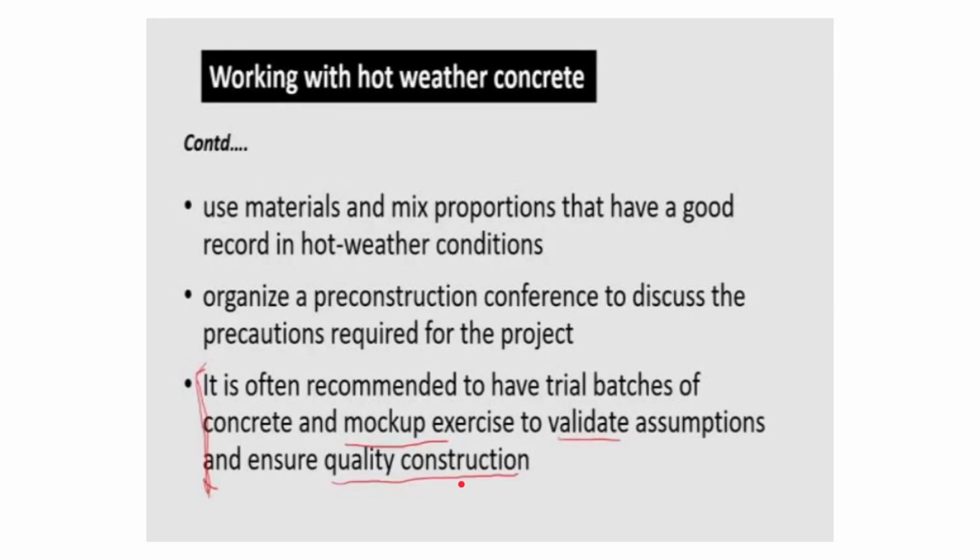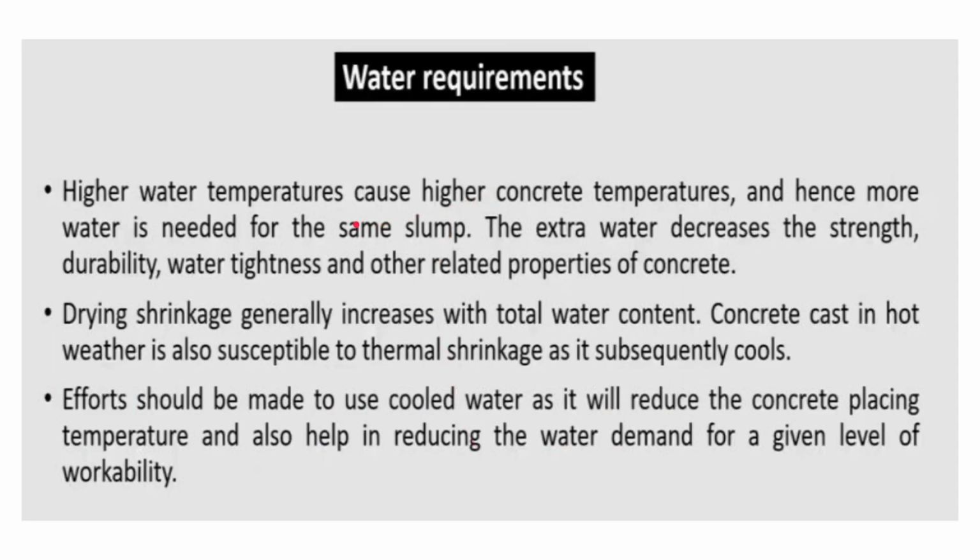Now let us come to the water requirements. As we studied, higher water temperatures cause higher concrete temperatures, and hence more water is needed for the same amount of slump. The extra water decreases the strength, durability, water tightness, and other related properties of concrete. So that is the basics.